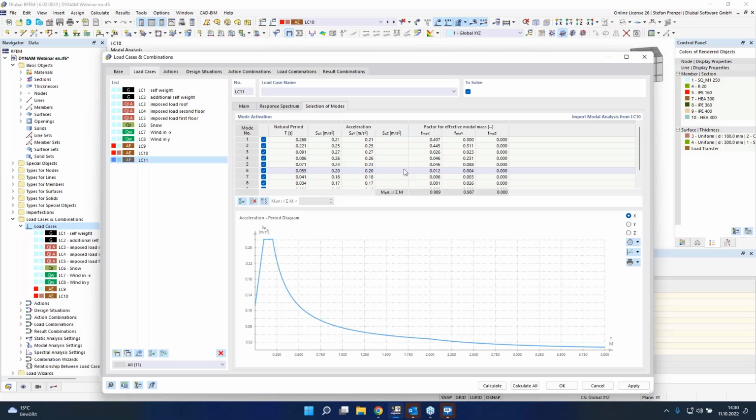And that's what we can do here also, just by clicking on deselect modes and use this value. So we want to use the 5% value. The program is already also over 90% in some of it, but we just need 4 eigenvalues for that. And that's the important thing. So that's also a performance point, just to use the eigenvalues which you need and not all eigenvalues.